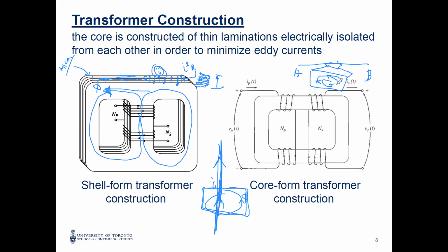They can flow in eddy kind of paths. This is the reason we call it eddy current. Okay, it's like a random current, randomly flowing from one point to another. How to minimize this eddy current and the losses?